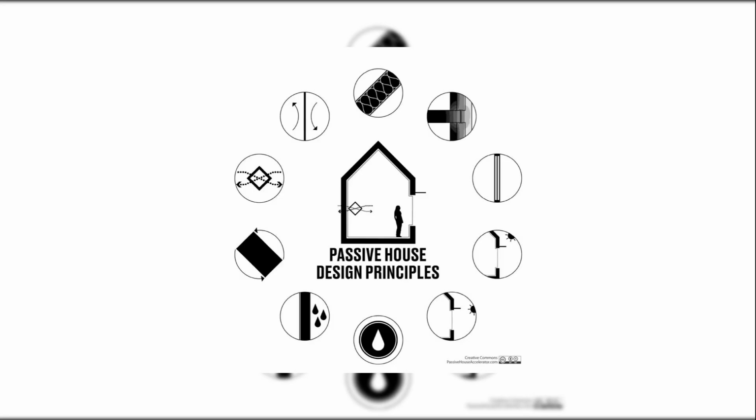The core principles of passive house. They are built around 10 guided principles. The first 5 are the classic 5: continuous insulation, no thermal bridges, airtightness, high-performance windows and doors, and fresh air with heat recovery. Then we add shading, orientation, daylighting, moisture management, and efficient water heating.